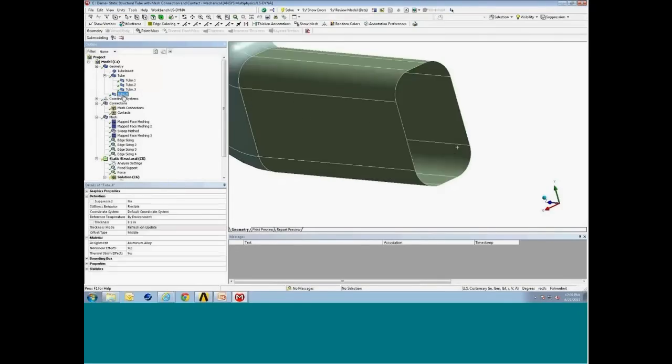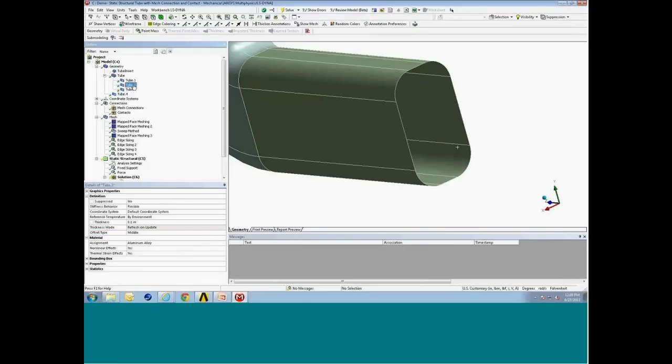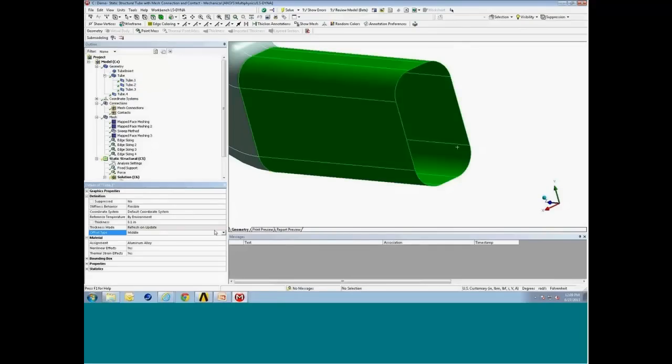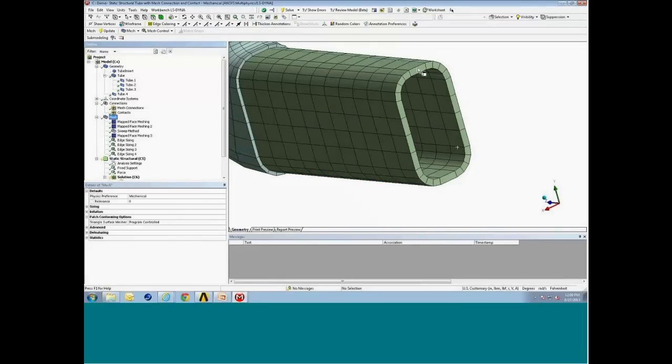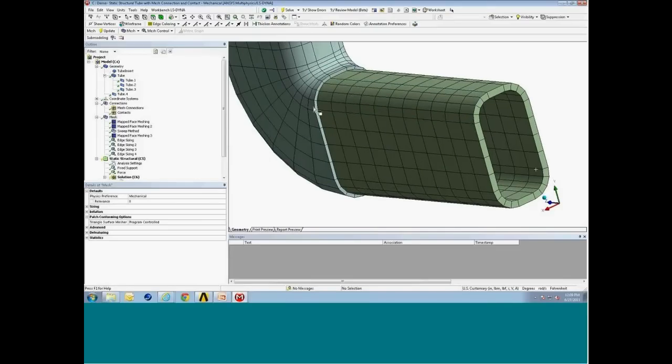Now, if we had our tube here and we set this offset, let's get to this body here. If we set this offset from middle to top, this surface body would actually be the top of the shell. You can define that, and then the mesh would be correspondingly extruded inwards. Now you can see the difference between setting the top, middle, or bottom representation of the surface body. So that's helpful in controlling that. You want to make sure you're modeling that properly. So that's the visualization with the shells.